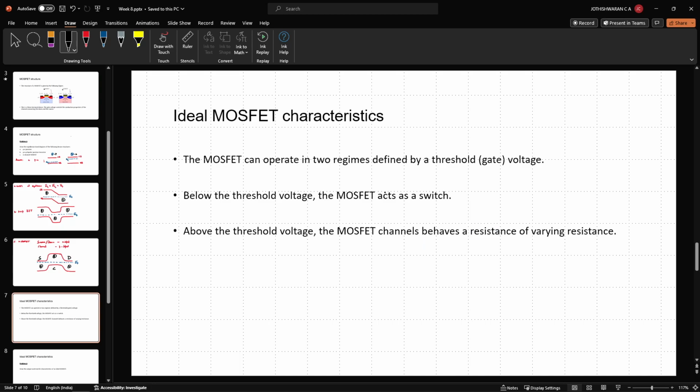Typically the substrate voltage is either matched to the drain voltage or the source voltage, but there are cases where the substrate is also biased at its own independent voltage. So all these cases are possible. Although it does not contribute to the current conduction, there is a fourth terminal in this three terminal device, but that voltage is never tweaked or tuned. It is usually kept at a fixed value. The threshold voltage is what we call VT, and this is applied to the gate.